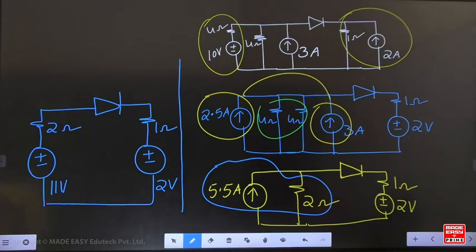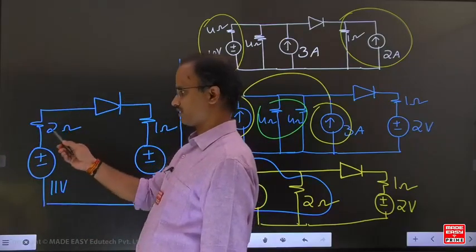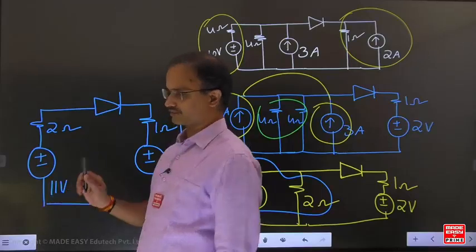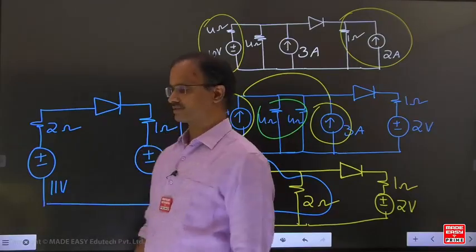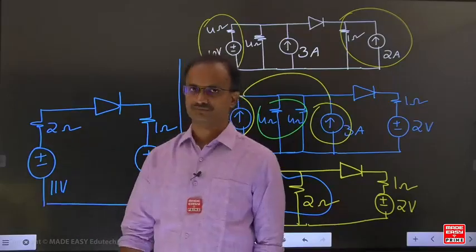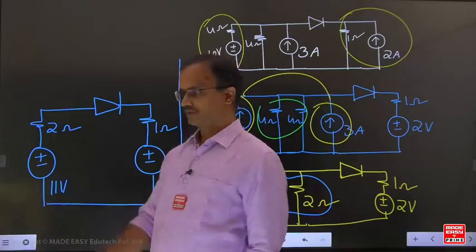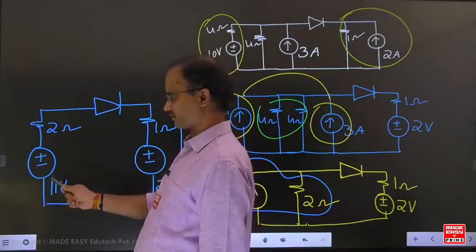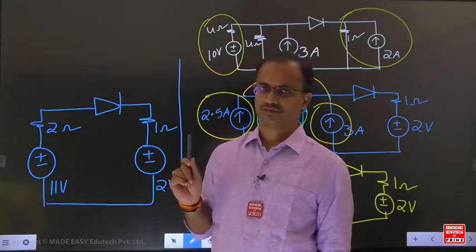Anywhere you can connect, no issue. Here also, dear student, don't get confused. Don't think that a resistance means the current is always positive. There is nothing like that. You can connect anywhere, that is your choice. But generally, in many cases, in representation, it is connected to the positive side. Why? Current flows from higher potential to lower potential. You can connect here also, remove the resistance here, connected in series to the negative terminal. The answer will not change.